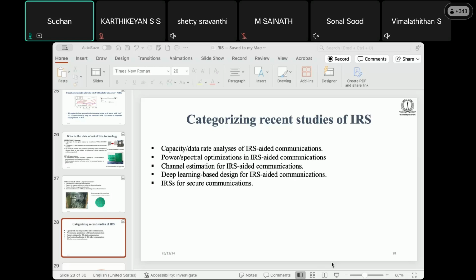So we do not need an extra RF chain at the IRS. That is our main objective: although you have massive MIMO and need to beamform to the IRS, still, if there is any obstacle, even after using massive MIMO, that obstacle can be removed by placing the IRS.